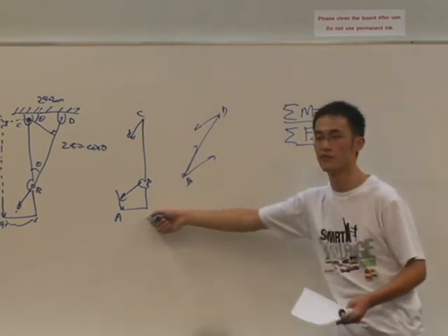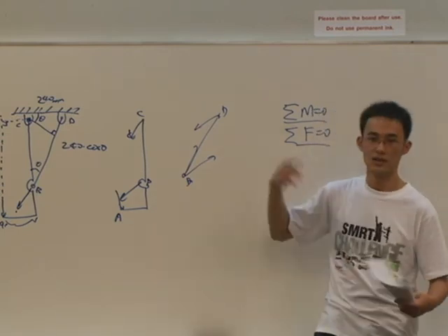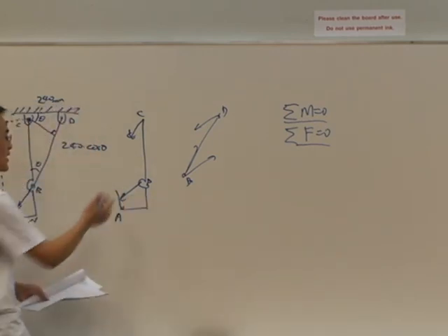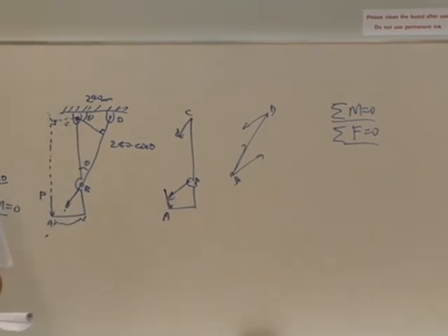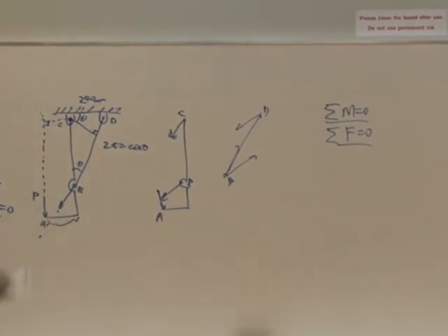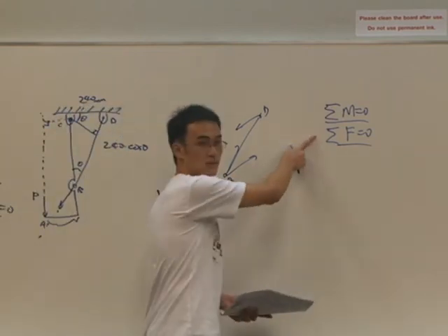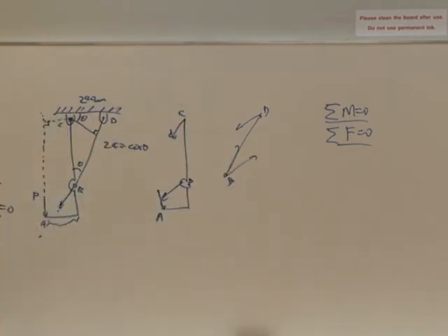It's the same for this one, where we also use the summation of moment to decide what the force at this point A will be. Everything links back to these two very important equations. These are the 3 steps for you to analyze a force in MOM, using the static equilibrium equations.